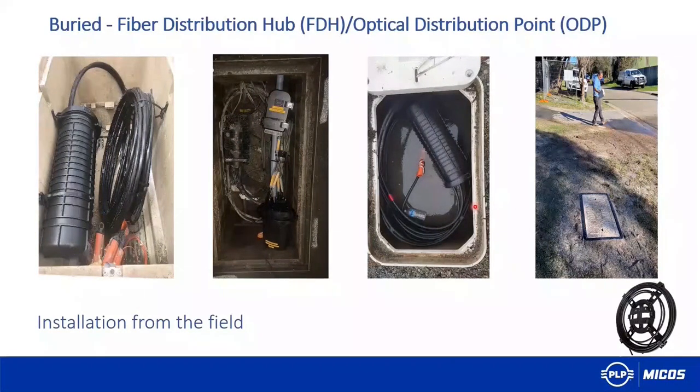These manholes are very popular in the UK. They have them all over the cities and villages, and they are using existing lines. So you can see they also have special holders in the UK. They call it a Mobra holder, where they mount the closure, and it's on a hinge, so you can pull it up, and it's still fixed in the Mobra holder, and you can open it and do the job without removing it from the manhole. And this is how it looks when it's in a green area. So I could talk more about manholes, about the maximum load, but this is not the subject of this presentation.